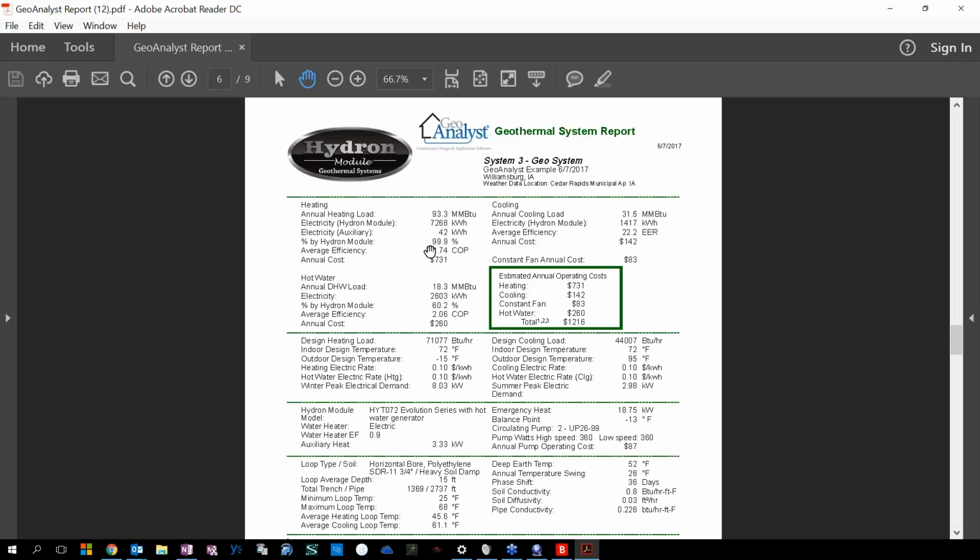Do you guys have that down in the U.S. at all? We do, actually. In Iowa, there's a co-op that requires the same thing. They require an 85-degree temperature difference for your calculation, and that you provide 85% of those BTUs looking at your bin data, or looking at your engineering data is what they typically use.